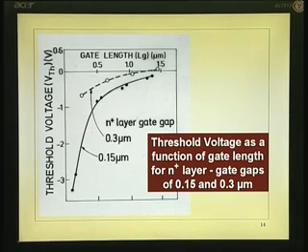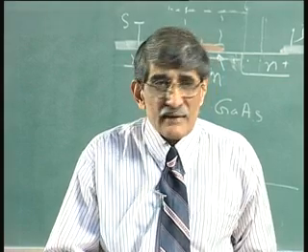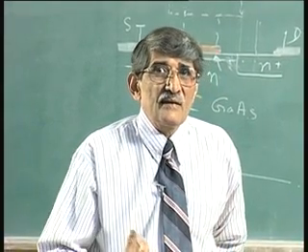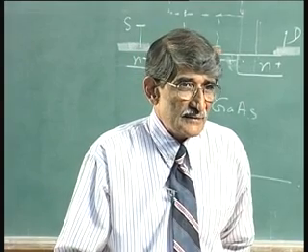So, you can see the impact of that more and more as you go into shorter and shorter gate lengths, because when you go down here the gate length and gap become more and more comparable. So, channel length is shorter and shorter, and you get the two dimensional effect much more here. So, in short channel devices there are two things one has to worry about. One is the curvature effect itself increases threshold voltage. Second one is the two dimensional effect of the electric field also increases threshold voltage.